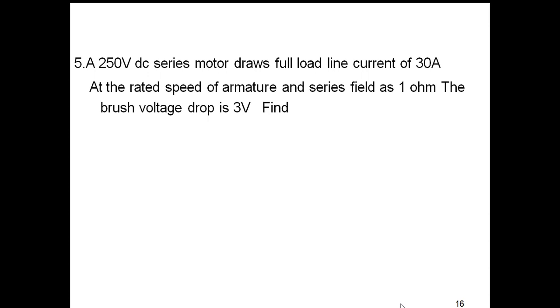Now let us see the next problem. A 250 volt DC series motor draws a full load line current of 30 amperes at the rated speed of 750 rpm. The resistance of armature and series field is 1 ohm. The brush voltage drop is 3 volt.